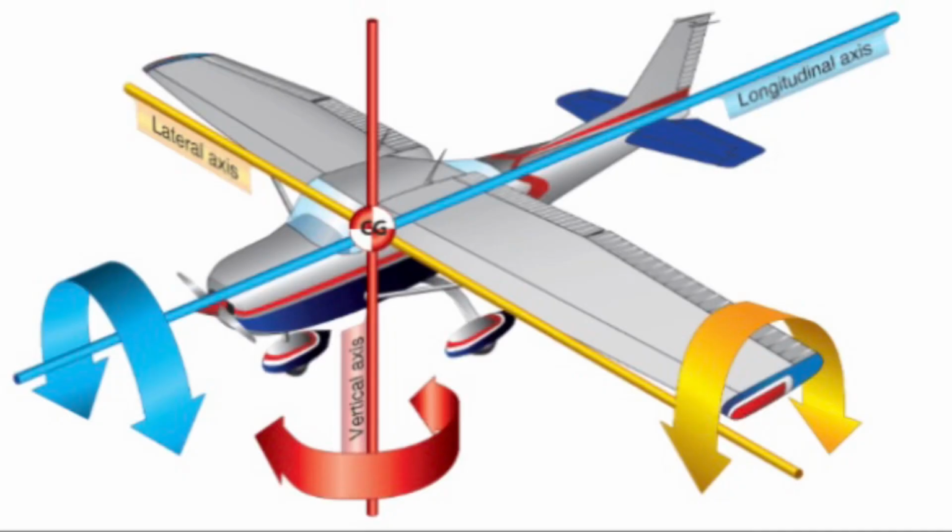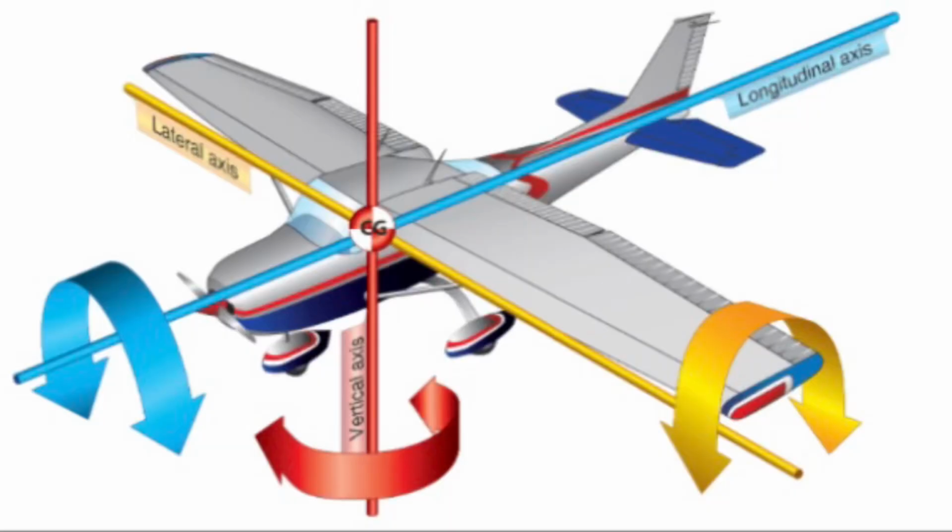Dynamic and static stability is about the lateral axis, which is also referred to as longitudinal stability. While talking about stability, it's also important to note lateral stability, which is along the longitudinal axis of the airplane. The three main things you need to know about lateral stability are heel effect, swept-back wing angles, and dihedral effect. First, let's talk about dihedral effect. Dihedral effect is due to the characteristic of the wing design, which tilts the wings upward slightly.